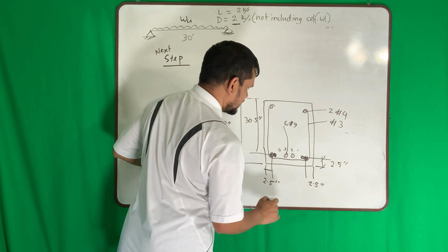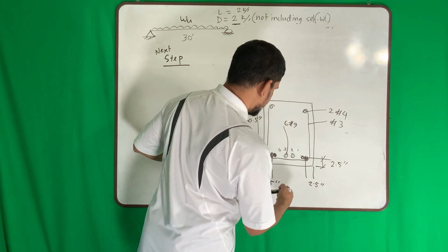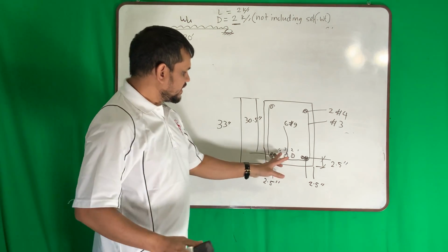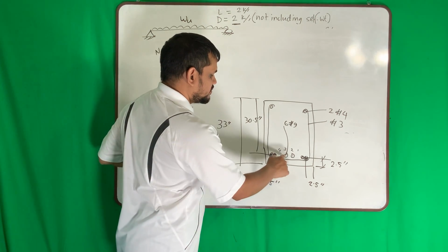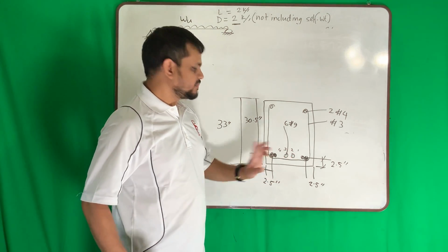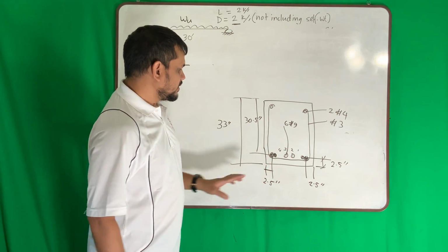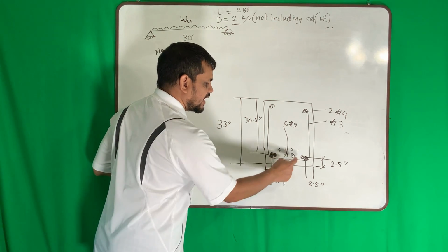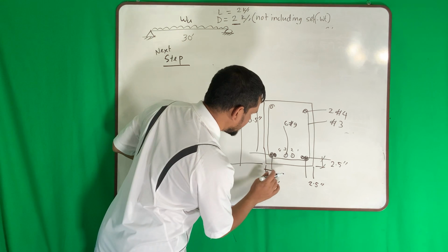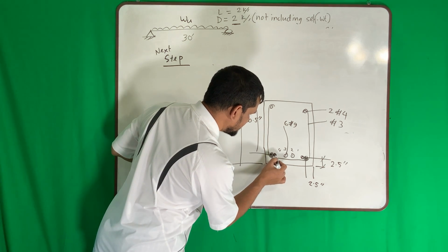Now, mostly we covered everything, tie bar, spacing, everything. As we bundle together, we should let the design site engineer know the exact spacing. Now, as we bundle this together, my spacing changes. I will have to calculate it. Calculate and tell this way.